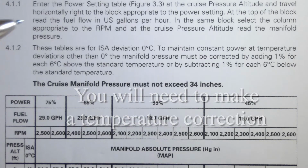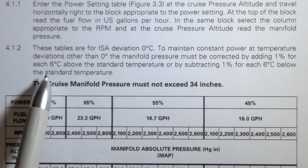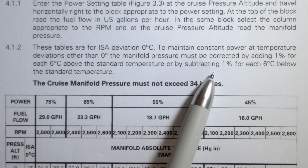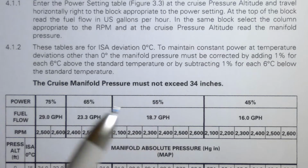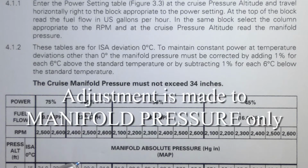That adjustment is to correct by adding 1% for each 6 degrees Celsius above the standard temperature, or by subtracting 1% for each 6 degrees Celsius below standard temperature. This adjustment is made to manifold pressure. We don't make it to anything else, only to manifold pressure.